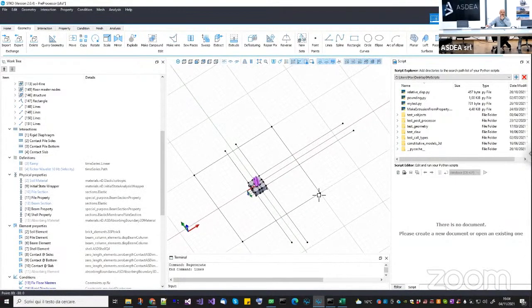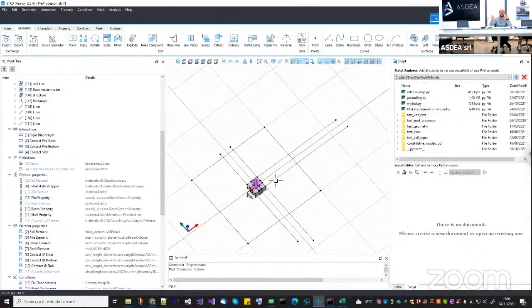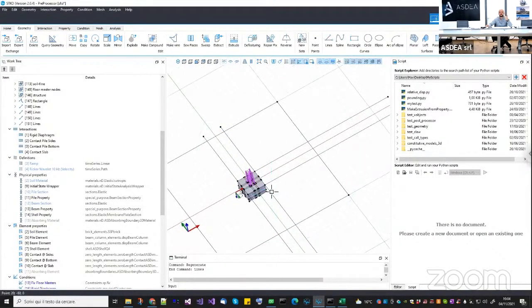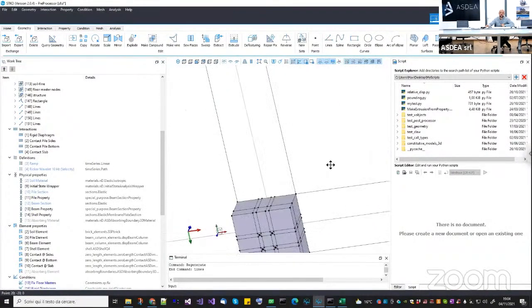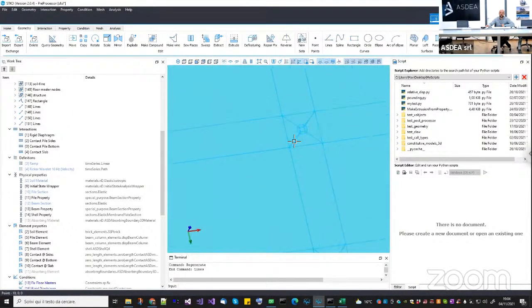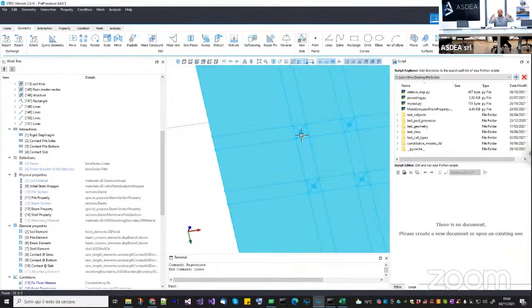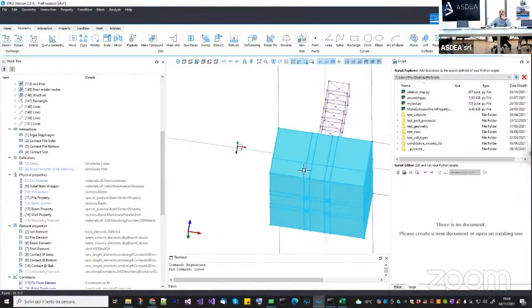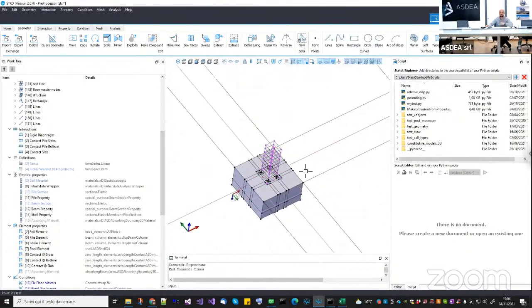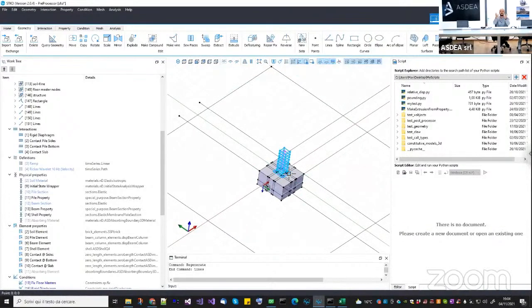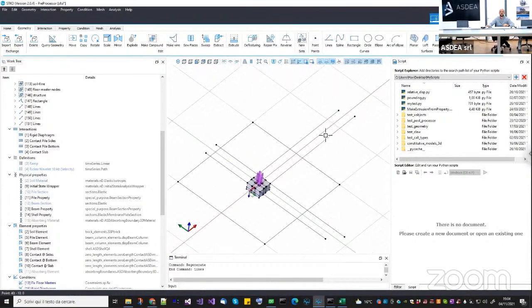Now, the nice thing about creating these two separated domains and then attaching them using this kind of transition is, first, that you can connect different mesh resolutions, but also that, due to the presence of the pile, as you can see, the soil domain is quite complicated, and if you want to enlarge it, you need to propagate this mesh down to the bottom. Actually, this is not necessary for the resolution at the bottom of the soil domain, okay? So if you want to simplify the model, you can just create a hole here, create a soil, and embed the detailed model inside the coarser model.